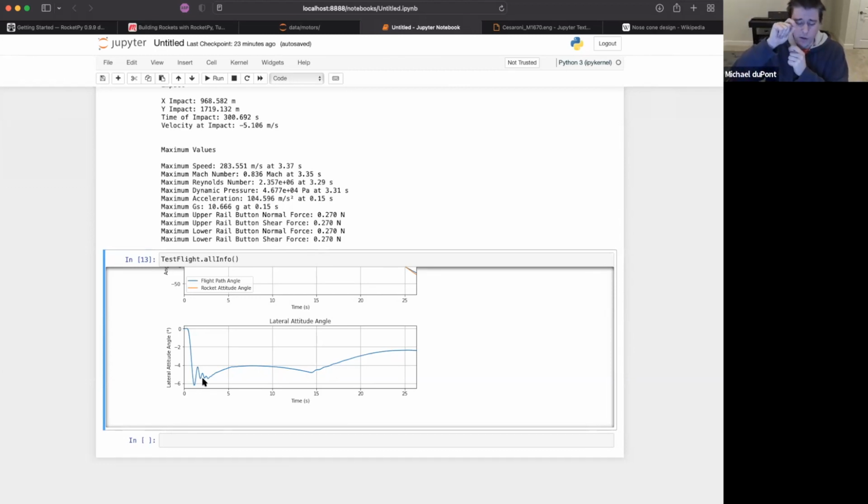And there are the 2 buttons that we added early on. As the rocket is first lifting off and getting off the rail it's mounted on, the thrust vector coming immediately down from the rocket is going through the center of mass, but it's to the side of the rail that we are launching off of.